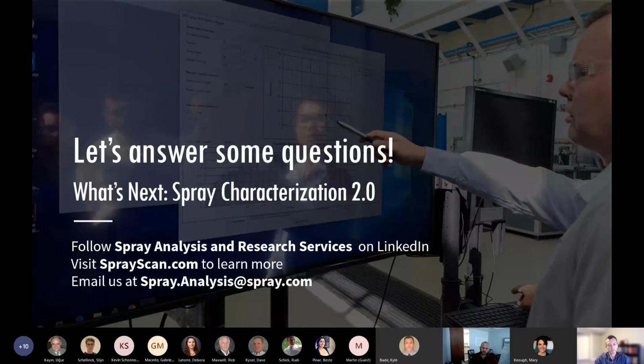Kyle, you brought up a valid point. And Deborah, thanks for that question. Visually, we can see the concentration of the spray. Let's say, for example, we see some heavy edges on one side and it's in a gas stream. If you can't replace the nozzle immediately, you can actually rotate that spray to where the bias is beneficial to your process. So that's another granular piece that you can use as a pivot.